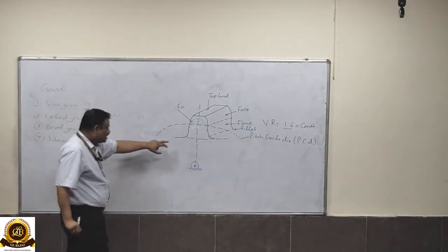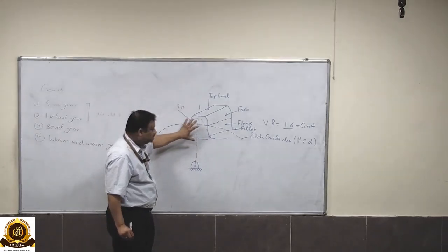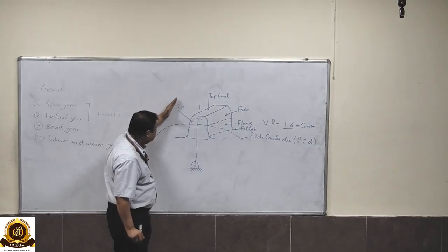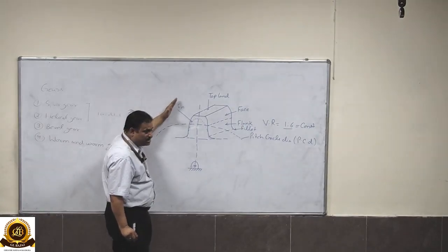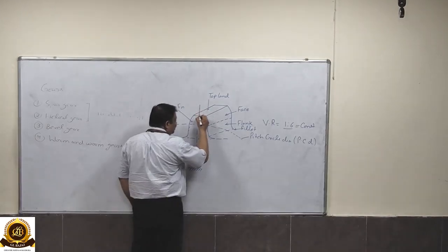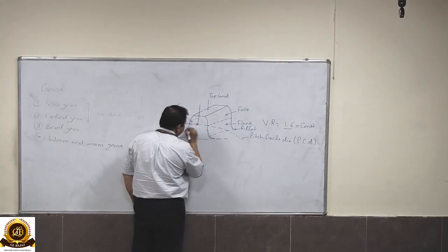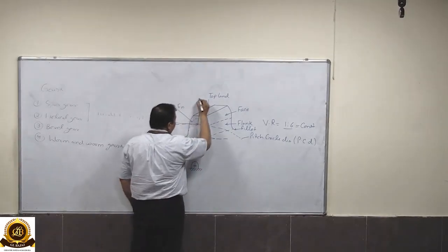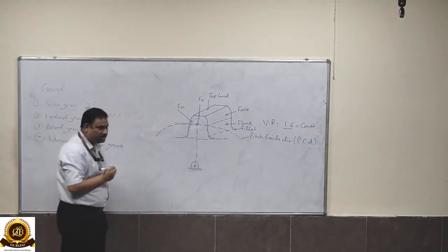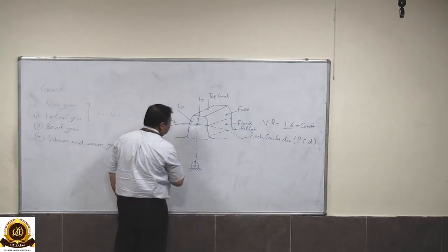So here I am using a parabolic curve to define the uniform strength of the tooth. During the engagement and the power transmission, this is subjected to a normal force of engagement, Fn, which is resolved into its two components, vertical component and horizontal component. Its vertical component is denoted with Fr, whereas its horizontal component is denoted with Ft.